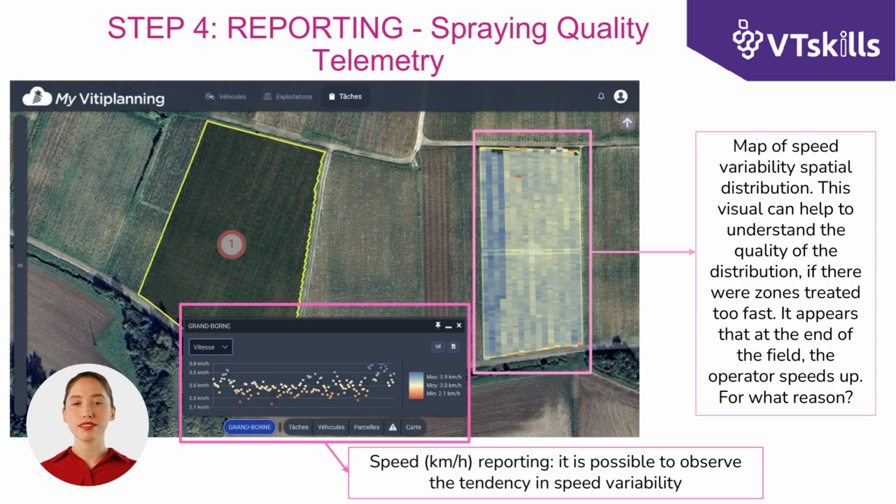Compared to the more obsolete constant pressure regulating units, they are equipped with a proportional regulating valve and additional section valves with calibrated returns, the former guaranteeing a constancy in the quantity distributed per unit area for variations in forward speed of up to plus 20%. At the same time, the latter prevents pressure increases and therefore the flow rate to the nozzles when the delivery of the mixture of individual boom sections is shut off.